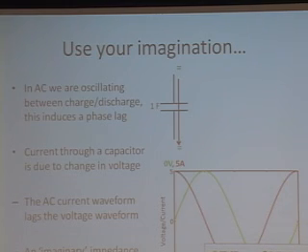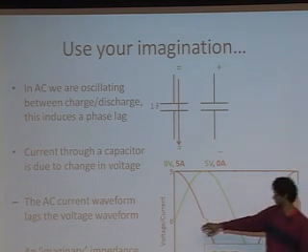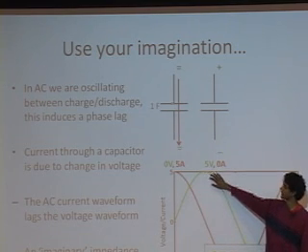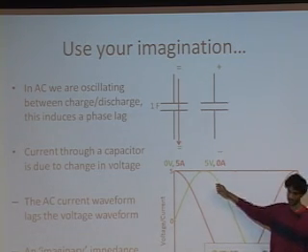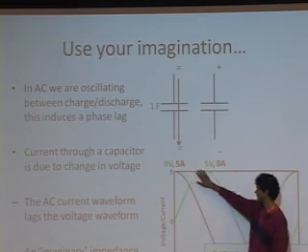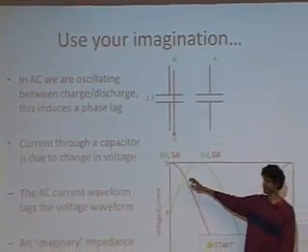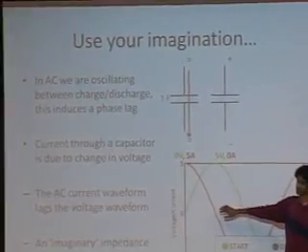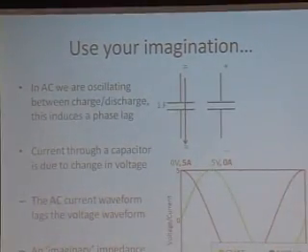If we start with one state of the capacitor, let's say the terminals are equal in voltage, so there's no volts, and there's current flowing through it, charging it. Let's say 5 amps, just a number I chose arbitrarily. Then after some time there's a voltage difference across the capacitor, so we go from 0 volts up to 5 volts. Now the current is based on the derivative of the voltage. Up here at 5 volts, at max charge, the derivative is 0, so now no current is flowing through this capacitor. The capacitor is fully charged.